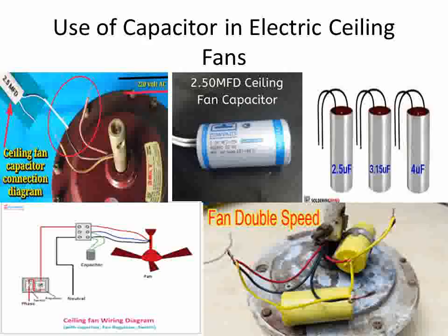If by chance the connection is wrong, meaning the fan starts rotating in the anti-clockwise direction, then the black wire of the input supply is connected to the other wire of the capacitor joined with the fan, and the rotation of the fan becomes just opposite to the previous one. This is used sometimes in the connection when we observe wrong rotation of the fan.